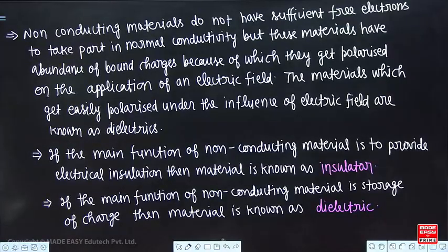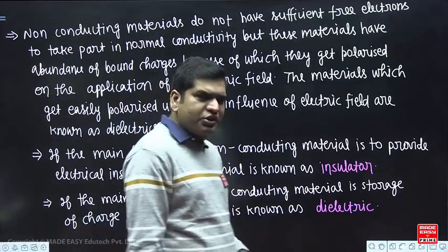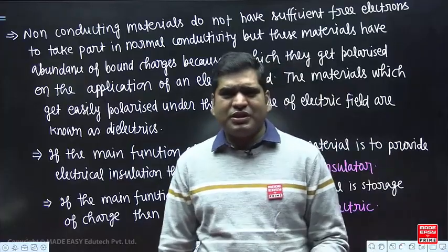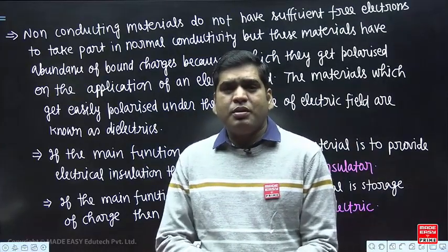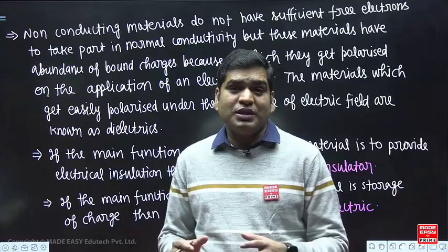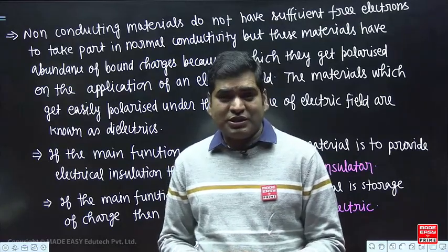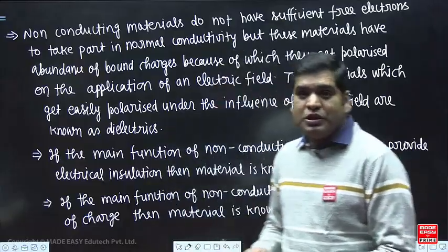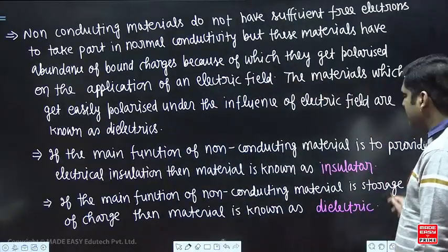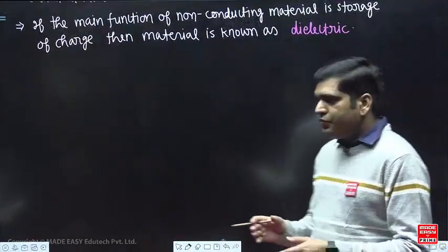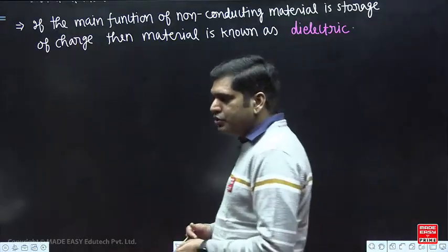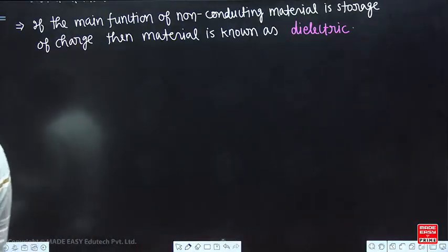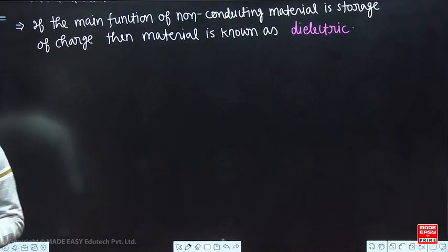Now we do not have to study much about the insulators, because in an insulator we are mainly interested in resistance. Reciprocal of conductivity is known as resistivity, but we want to explore the dielectric nature of non-conducting materials. So we will explore things from the dielectric point of view. Dielectrics are basically materials filled between the plates of a capacitor to increase its charge storage capability. This is the first slide.